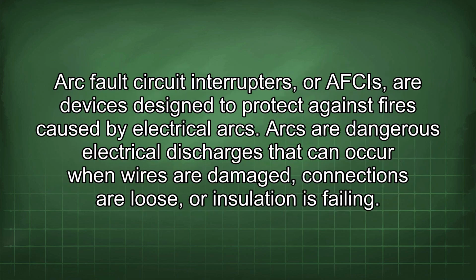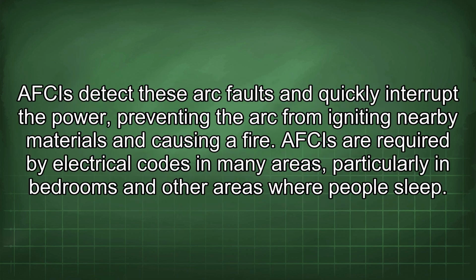Arc fault circuit interrupters, or AFCIs, are devices designed to protect against fires caused by electrical arcs. Arcs are dangerous electrical discharges that can occur when wires are damaged, connections are loose, or insulation is failing. AFCIs detect these arc faults and quickly interrupt the power, preventing the arc from igniting nearby materials and causing a fire. They are required by electrical codes in many areas, particularly in bedrooms and other areas where people sleep.